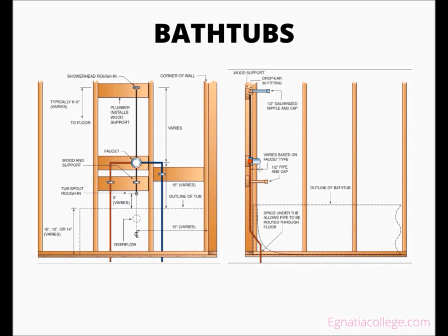A manufacturer provides installation instructions indicating where the faucet is in relation to the finished wall. Many walls that surround a bathtub are tiled or have a solid surface such as marble. A plumber must read the instructions before installing a faucet in a wall during the rough-in phase to avoid accessing the wall for corrective action during the trim-out phase.